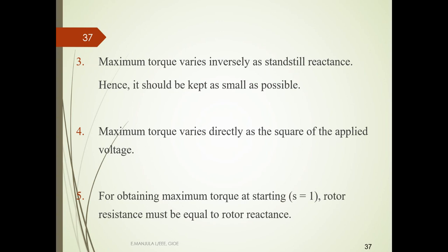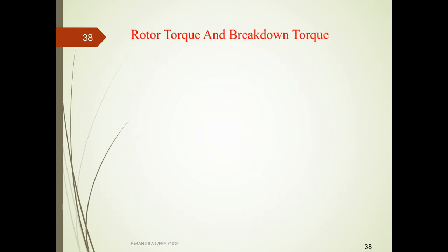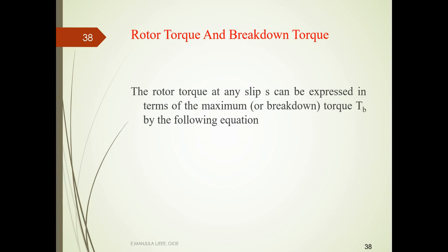To obtain maximum torque at starting, we need S equal to 1. Where S is equal to 1, X2 is equal to R2. The rotor resistance must be equal to the rotor reactance. So the rotor reactance must be equal to the rotor resistance.